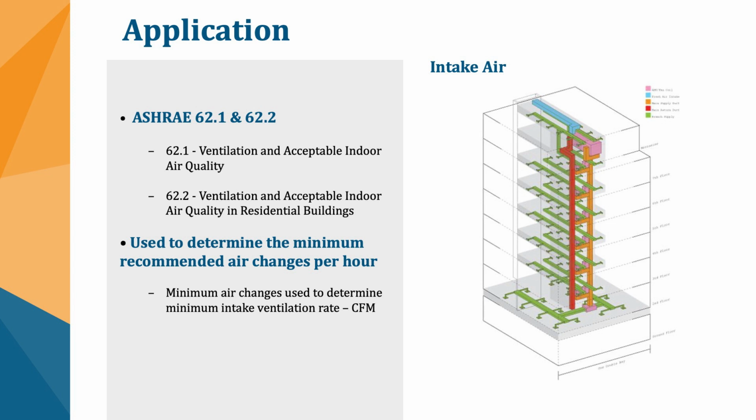You can certainly do it that way, where you just have the fan run for a certain amount of time, and then that fan either shuts down or the intake gets closed off and you're recirculating conditioned air until you want to open up and get a new change of air.